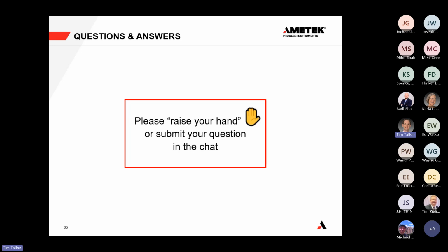For things like coal, it'd be more important to have a combustible measurement. For things like biomass, again, combustible measurement. But if you light off with hydrocarbon, then I'd recommend monitoring for hydrocarbons. I hope that answers your question. Good question there related to the hydrocarbon measurement.